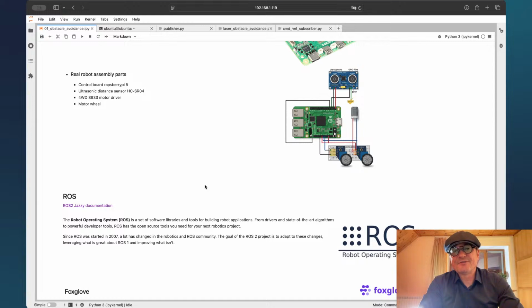For example, if the angle between the robot and the wall is too small, the ultrasonic sensor can skip the signal, but LiDAR provides measurements not only in front of the robot, but also at different angles, including 360 degrees. Degrees, yeah, I got you. Okay, thank you.